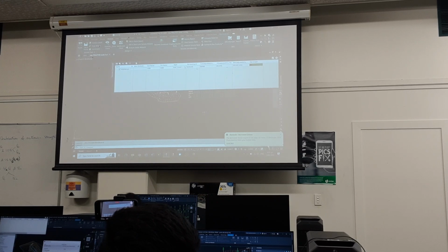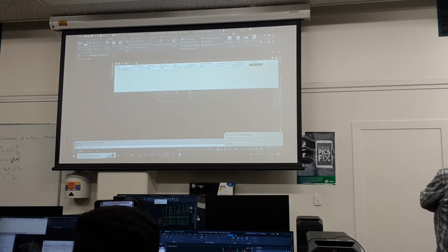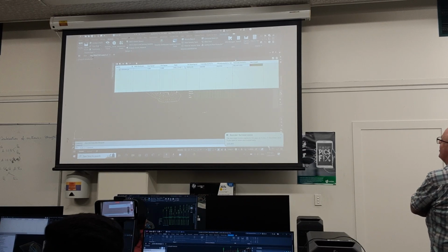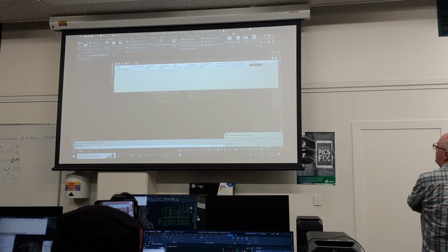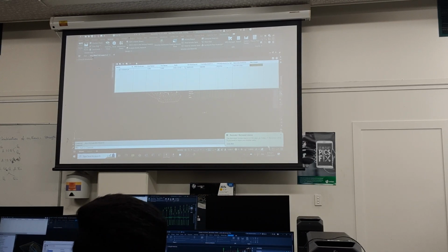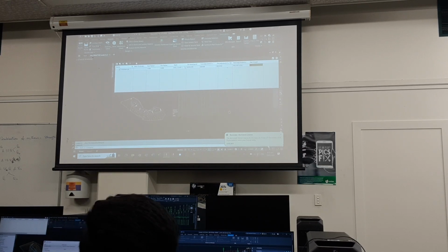and it brings it in, and it says cut 68, fill 262, giving a net fill. You see the green is way too much. So that's not very good. You need about 20 truckloads of dirt. Yeah. That's several hundred or thousand bucks. So let's see what we can do about that.